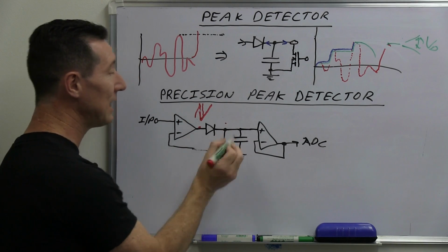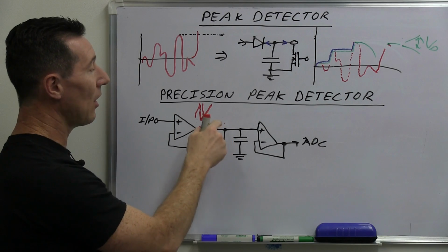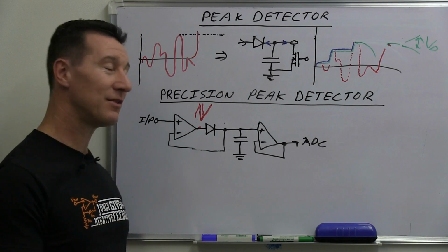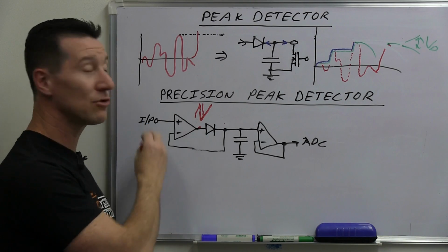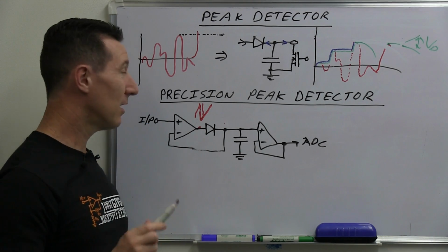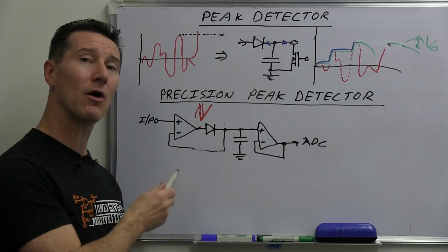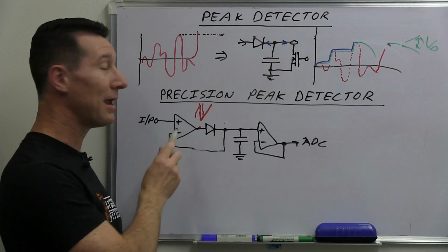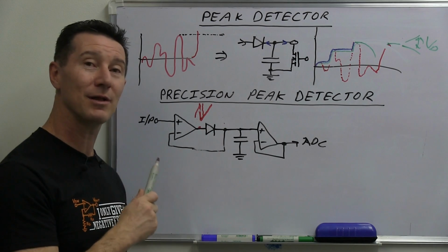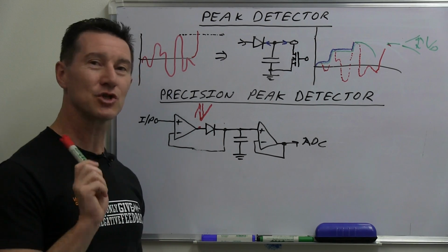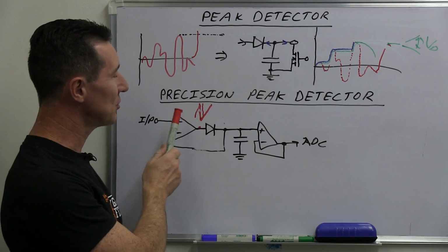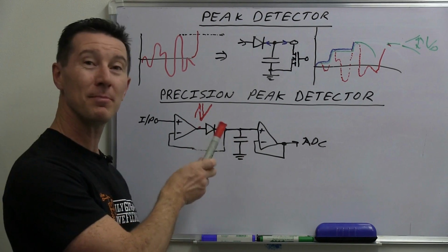The output voltage here then won't go immediately up to the value. There's going to be some slew rate in there, and if you're working on fast signals, for example, the slew rate of the op-amp is going to matter a lot. So you've got that recovery time in there of this op-amp, and that, for a lot of circuit applications, can be a real big deal. So naturally, that leads to a trade-off between how fast this op-amp is and what value capacitor you use.